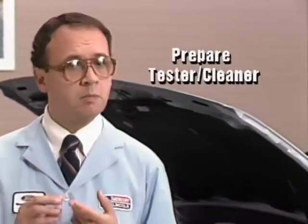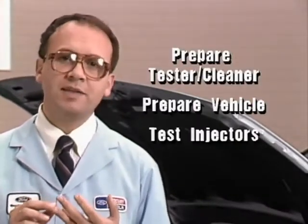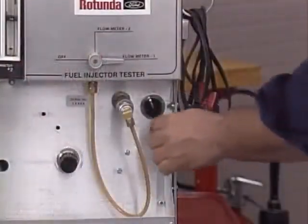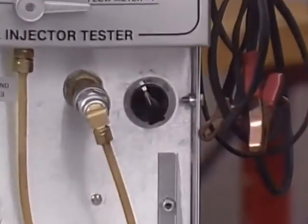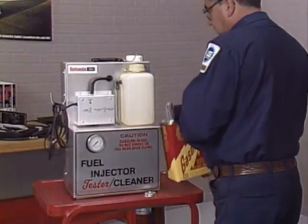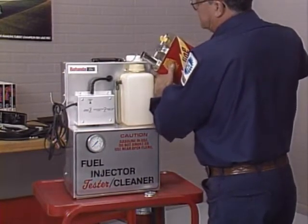Now, testing the injectors is a long procedure, so we'll break it up into 3 parts: preparing the tester cleaner, preparing the vehicle, and testing the injectors. So, let's get started. The first step is to make sure that the manual shutoff valve on the tester cleaner is off. Next, add clean, unleaded gasoline to the tester cleaner tank.